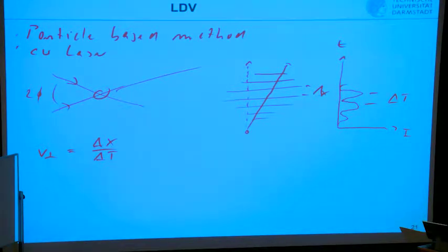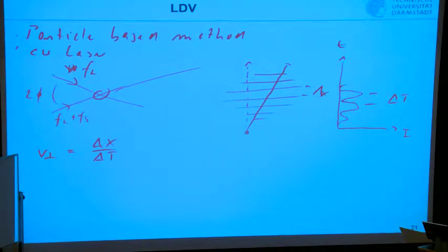We have seen that with that approach, you would not be able to distinguish whether the particle comes from the top or the bottom. And that's why you have here not exactly the same frequencies. Let's say, to take f, the laser frequency, the other one has a slightly different frequency, which is shifted by a Bragg cell that we have seen is made of an acousto-optic modulator, where you change the frequency by the interaction of the light wave with an acoustic wave. And with that approach, you're able to measure at single locations, the probe volume.